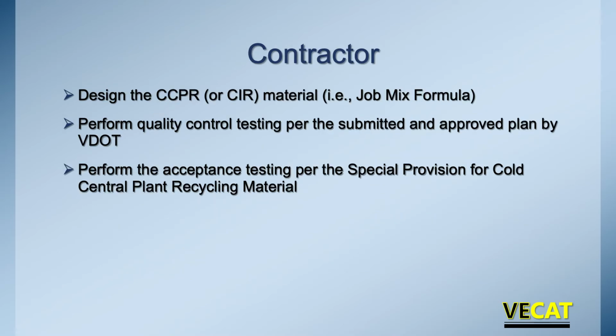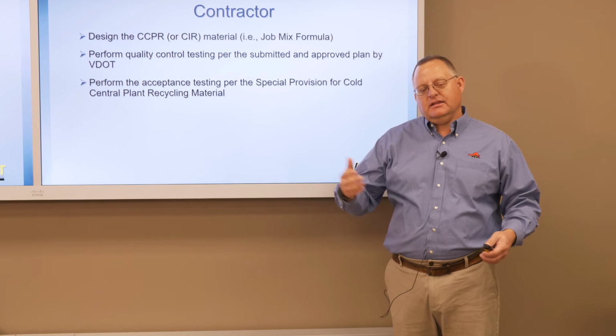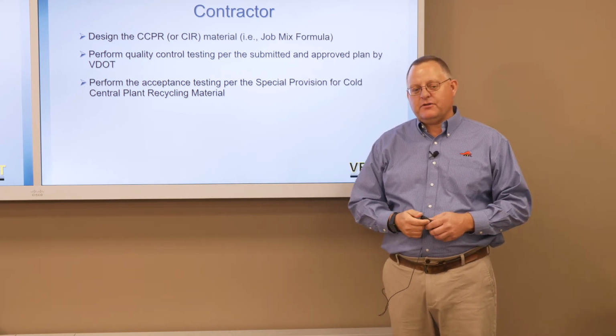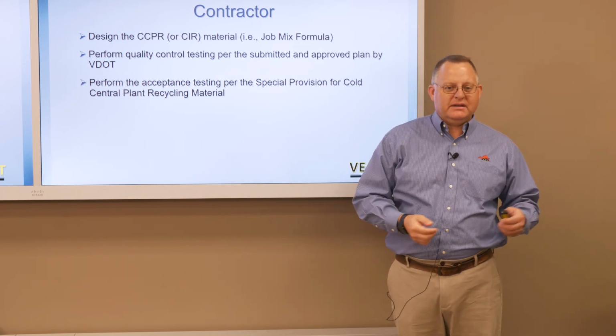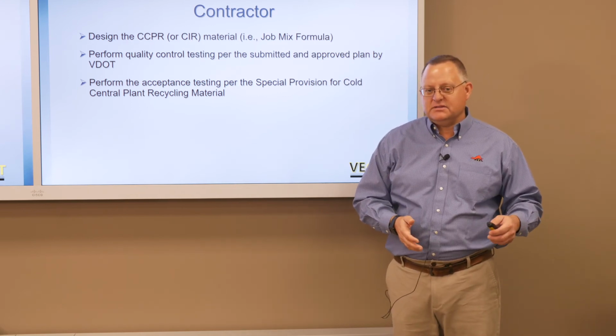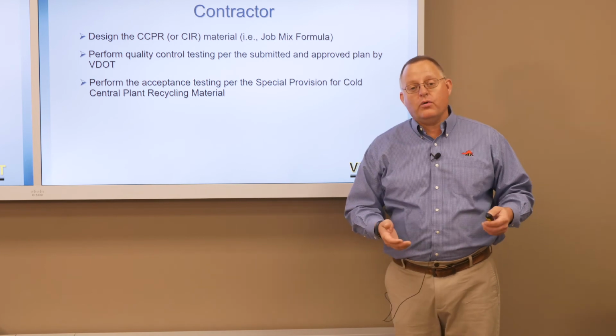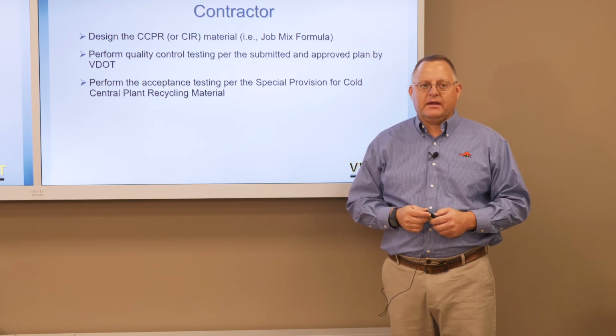So what does the contractor do? By spec, they're designing the CCPR, the cold in place recycled material, and they're putting it together and submitting it in a job mix formula. What's different with cold recycling than traditional hot mix asphalt, conventional asphalt mixes, is there is not a specification requirement for a certified mix designer. Currently, only certified mix designers are necessary for asphalt mixes, but for cold plant recycle and cold in place recycling, there is no specific requirement per VDOT spec.